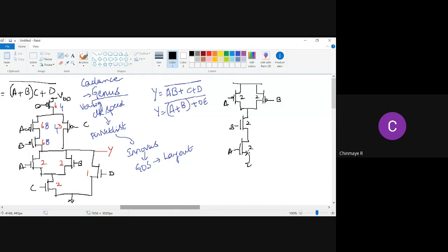Let's also write the capacitors here. Since this is 2 at the input of the gate, you will have 2C. In fact, you should write the combination of both. Here also due to PMOS, what's the capacitance here? Gate capacitance of PMOS.